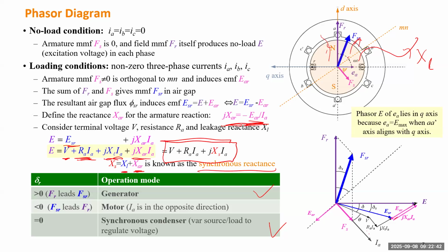So remembering from the previous session, we developed the formula to calculate real power over a transmission line. So the angle difference tells how much real power you deliver. If the angle difference is 0, so if this V and this E are in the same direction, there's no real power. We just call it delta, just indicating their angle difference.